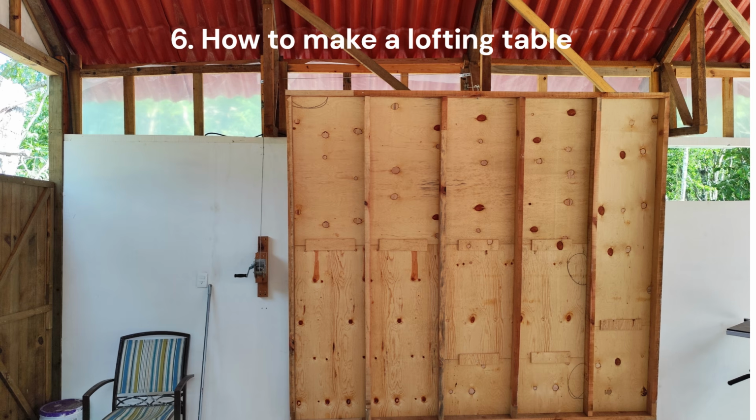When you are finished with the process of lofting, you store away or destroy the lofting table. We at Jungle Ranch have solved it by raising up the lofting table. When building your lofting table, try to use as little wood as possible, but strong enough. You can use 2x4 frames and space each frame 600 millimeters. If you want to investigate how other boat builders made their lofting tables, just search on YouTube.